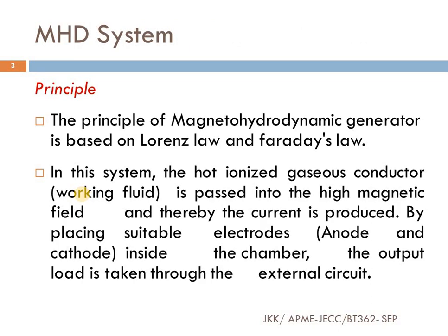The working principle is actually Lorentz and Faraday's law. In this system, what we utilize is a hot ionized gaseous conductor. This hot ionized gaseous conductor passes through a magnetic field so that a potential is generated in that conducting fluid. And this generated EMF, or potential, can be extracted towards the outer electrical circuit.